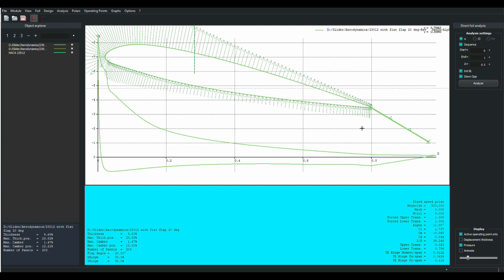And you ask, why didn't I keep that here? Well, the flow conditions weren't fully understood in my mind, and I built a hinge type that is traditional in general aviation as being a high performance type hinge, and I wanted high performance. This control method with a flat plate is not as efficient, but effective. Those are two different things. One's associated with a lot of drag and reduced lift, and the other one has to do with: are you getting pitching moment? Are you keeping the flow attached? Are you doing the job you're supposed to do in controlling the aircraft? And the answer for flat plate is yes.